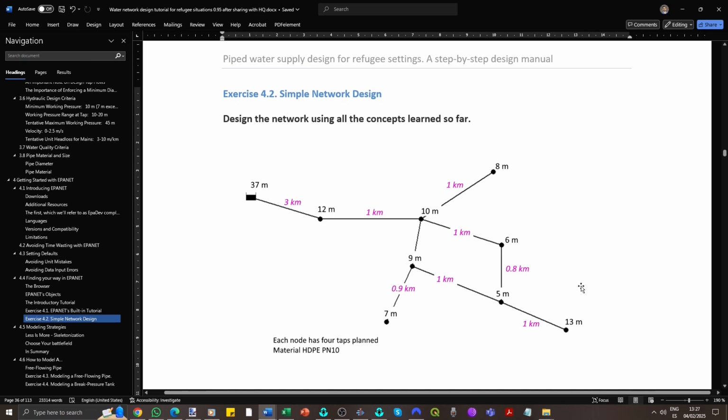Note that while the Sphere standards specify a minimum of 0.125 liters per second, this would require 9 hours of distribution to supply the minimum prescribed amount of water, which is unlikely in most camps where distribution lasts 5 hours at most. 0.2 liters per second is better suited to site realities and avoids issues.